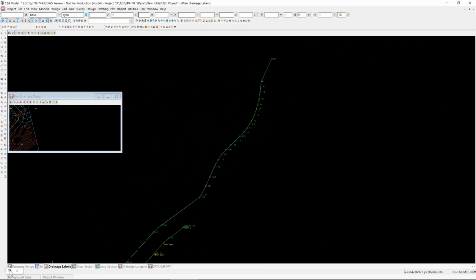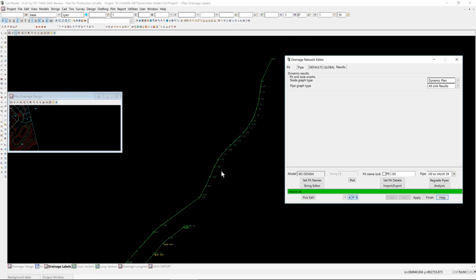So the way you would handle it is, your water authority will give you a pressure that they can sustain at a particular node in the network. So in this case, up to the top middle of the screen there would be one break-in point, one tie-in to the existing network, and they said that had an elevation of, I think from memory, 137 metres.